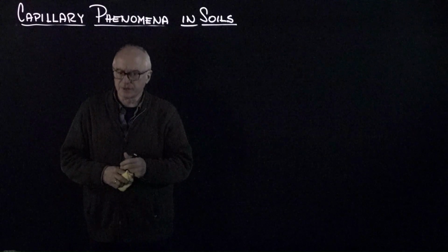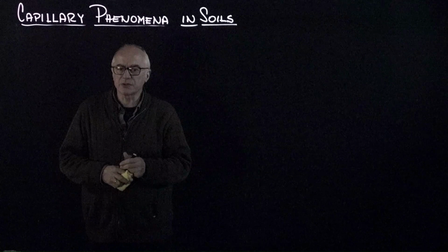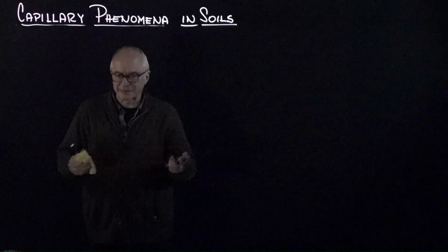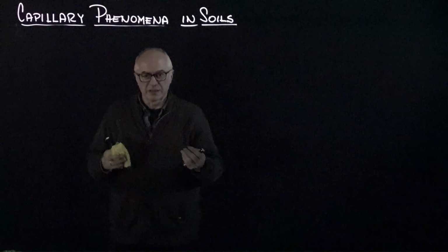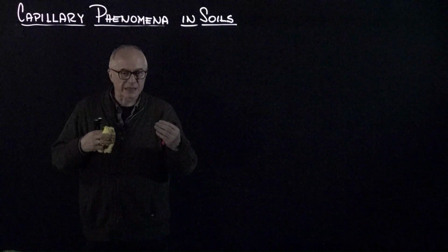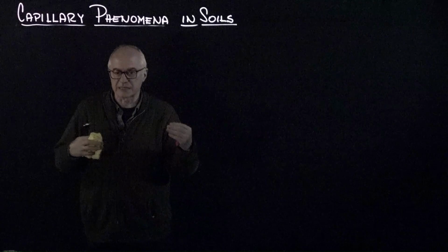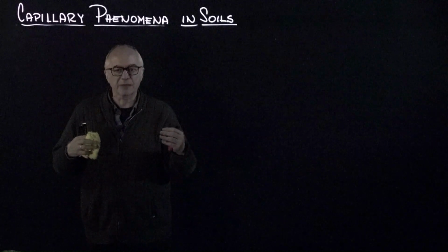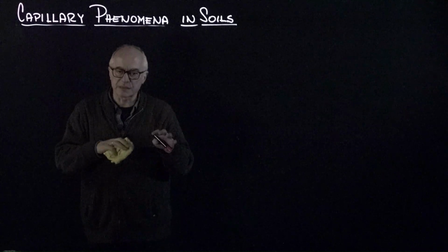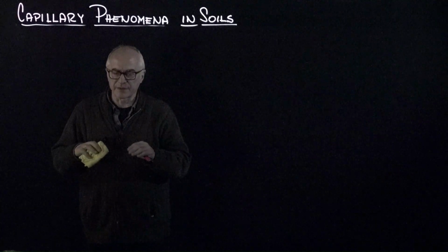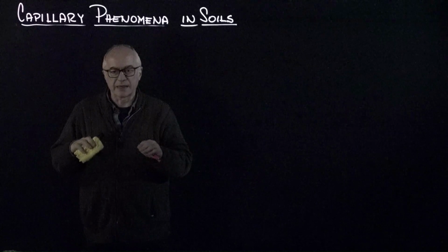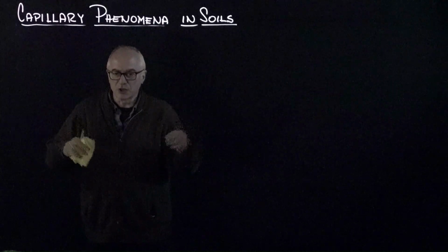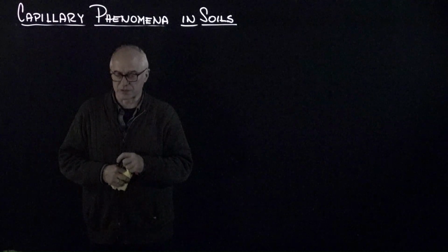The previous video introduced the concept of capillarity and the two fundamental parameters: what happens at the interface between two immiscible fluids, which is the surface tension, and what happens when these two immiscible fluids interact with the third one, the substrate, and now they form a contact angle as the balance between the three interfacial tensions.